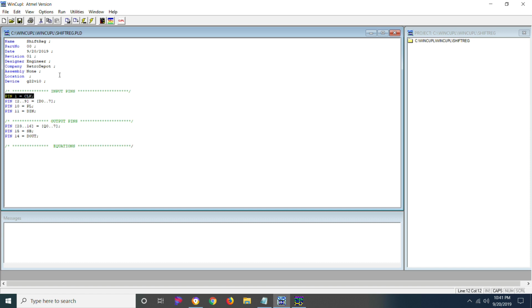So one thing that I thought about is that this clock pin should only go low when you have a situation where either the clock is low, the chip select is low, or they are both low. An easy way of doing that would be to use an AND gate on the input to the clock. On one input to the AND gate, you would have your baud clock.